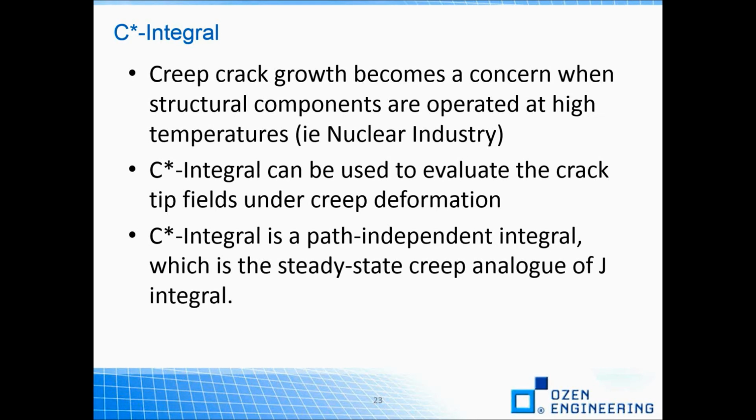Crack growth has been relatively recently considered as a branch of fracture mechanics over the past 40 years, and it generally becomes a concern when structural components are operated at high temperatures. As an example, you can think of the nuclear power plants industry, where parts are operating at high temperatures.